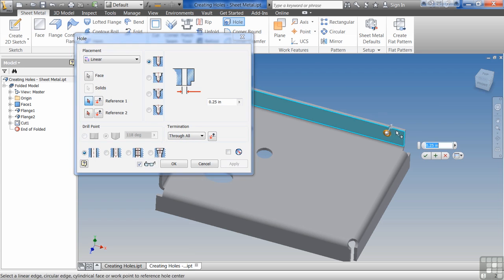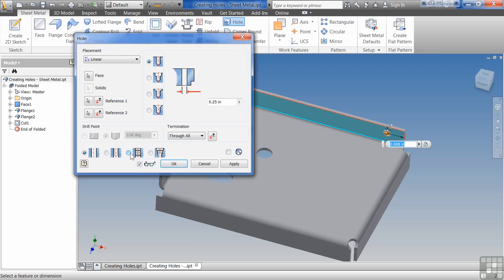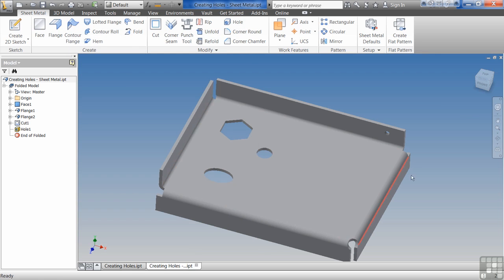For example, if I come in here and I put a hole in, and I put this information in here, and it's actually a threaded hole, whenever I go to dimension this on the drawing, I can click on the hole and it'll say this is a hole with this size threads. Whereas a cut in a sheet metal isn't going to understand that it's a hole. It's going to understand that it's an opening. It's a subtle difference, but the reason I mention that is because I encourage you to use the actual hole command whenever possible.